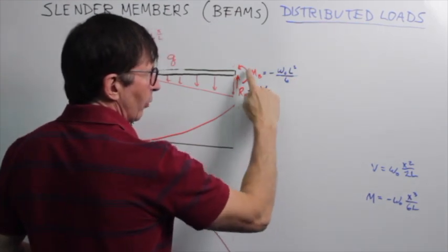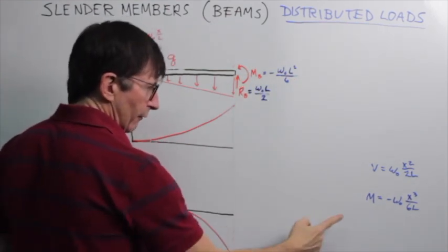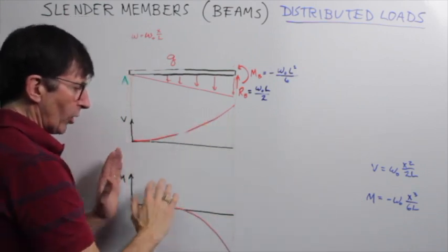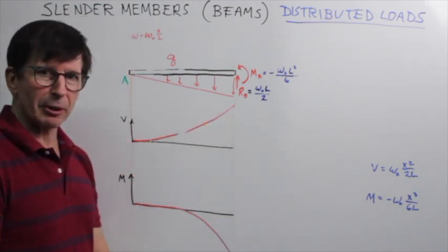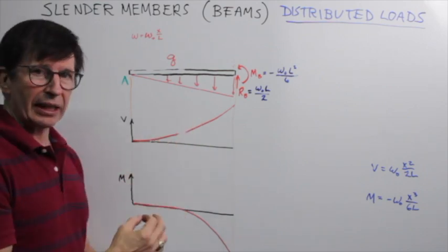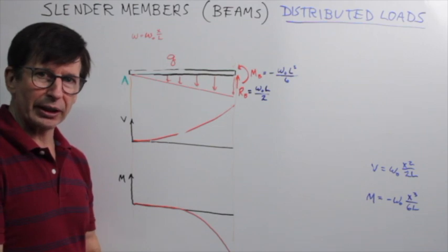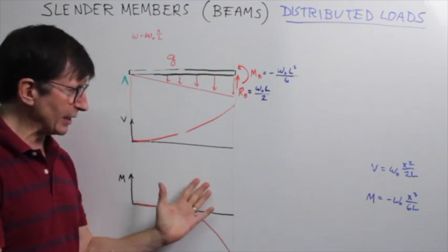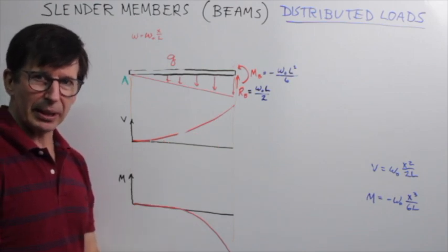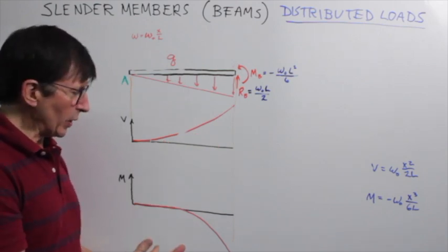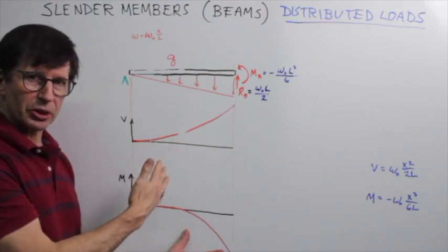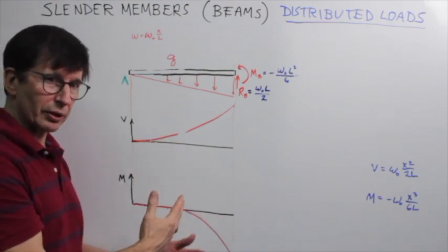Negative, that checks out with the value we know to be on the right from the equation. So the equations seem to be right. The form of the graph seems to be right. Now we know shear and moment at every station. And we will see later in, I guess, chapter 6, how we take these values in order to get the stresses in the beam. So let's take a look at how we know what the relationship is between the values and slopes of these respective curves.